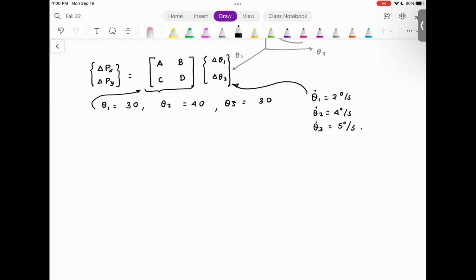And if you go to avionics, this frame matching is a very critical problem, because every system, and even in robotics, every system works at a different update rate. So if you want your robot, suppose a high-speed robot, to behave consistently, then you need to match the frames. You cannot take the velocity from one frame and the angle from another frame and try to find the answer. That would make the robot unstable. Many times, the sensor data coming at you may not come in the same frame, so you have to be tolerant to that. You have to use some type of error correction and make sure that you are getting this data in a consistent frame.